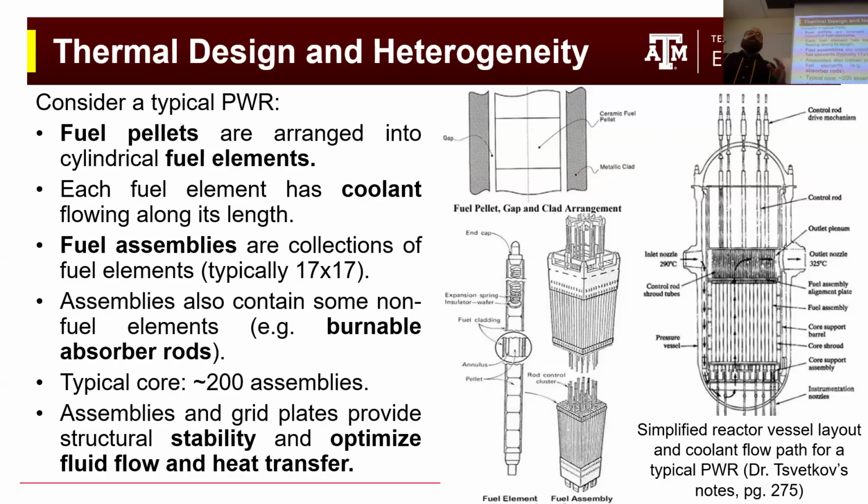And those spacer grids are designed to trip up the flow and add more turbulence, because more turbulence allows for more mixing, and that allows for better heat transfer. So there's kind of a lot going on. When you see this assembly, it might look simple, but there's actually a lot of details behind why we set these things up the way that we do.